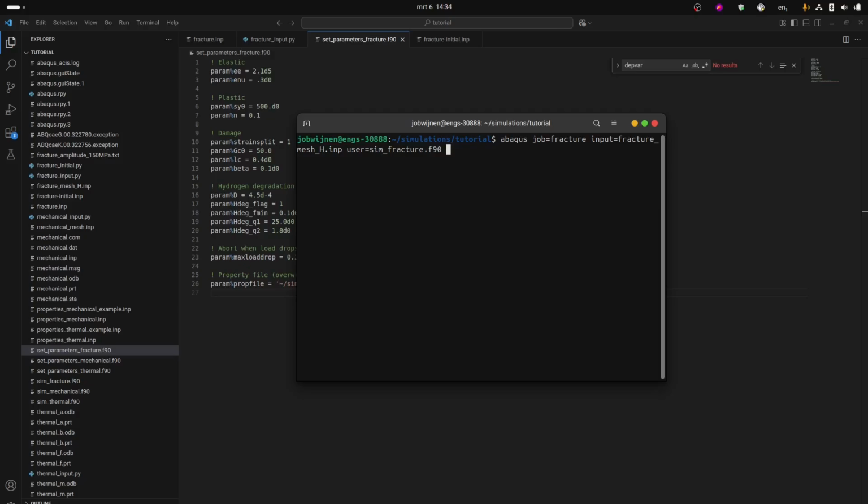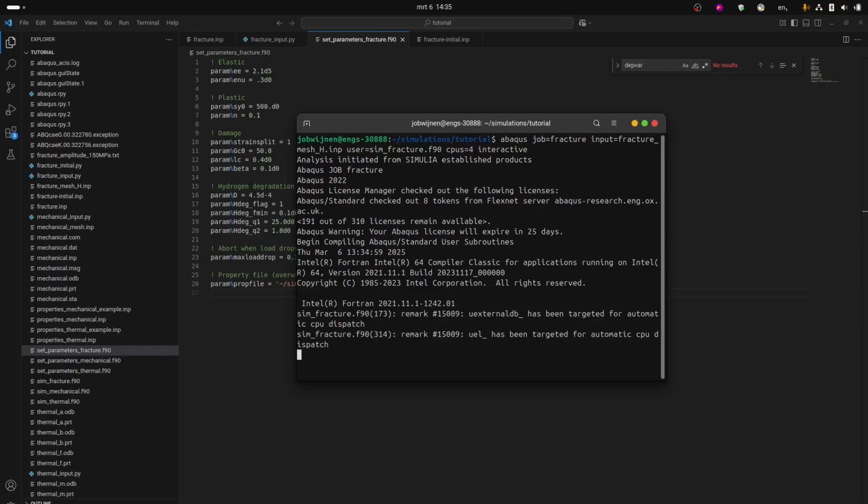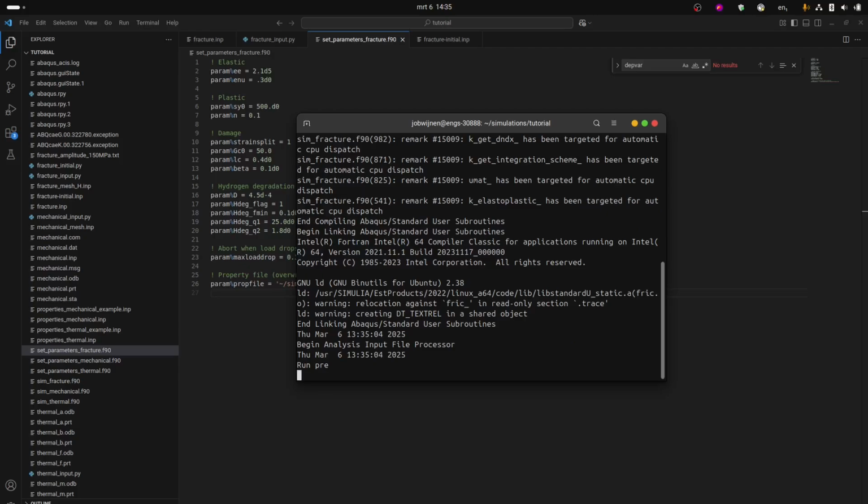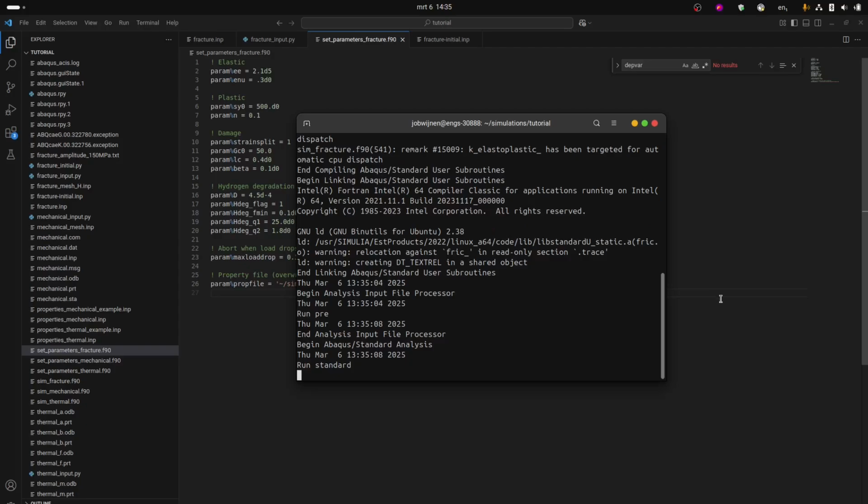Since these simulations are relatively big, we can also specify the number of CPUs that we want to use. Typically for the size of simulation that we're using now, up to 4 CPUs speeds up the simulation. After that, it saturates. So using more than 4 is usually not really beneficial. So let's use 4 right now, and keep it running in the command prompt. We use the interactive command again. So it's compiling now. Let's see if it starts running without problems. Yep.